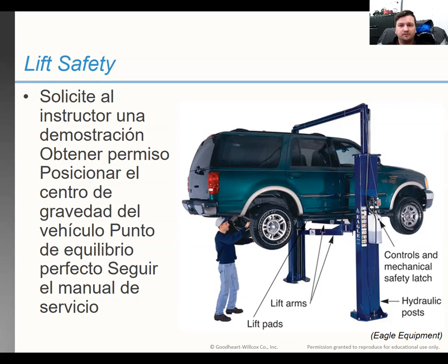So lift safety, you want to raise the vehicle slowly. Keep your fingers clear of moving parts. Double check your lift points and make sure the vehicle is level. You always want to keep your hands clear. When you're raising it up, it's just a button you're going to push. That's the only hand that should be up there, pushing that one button.